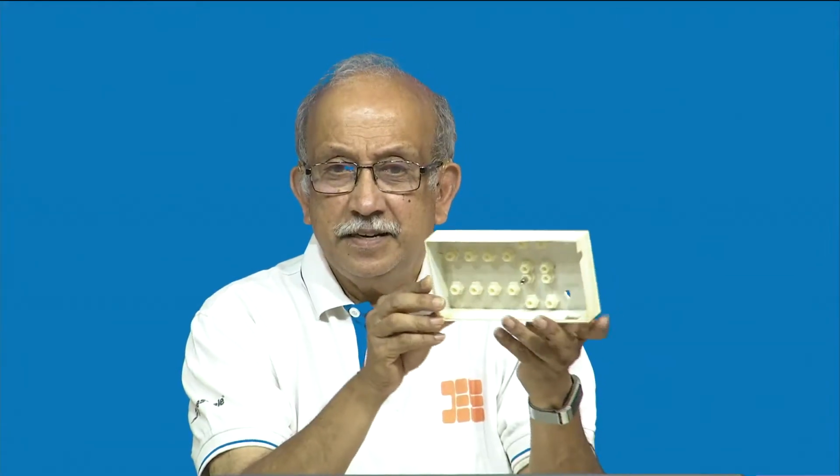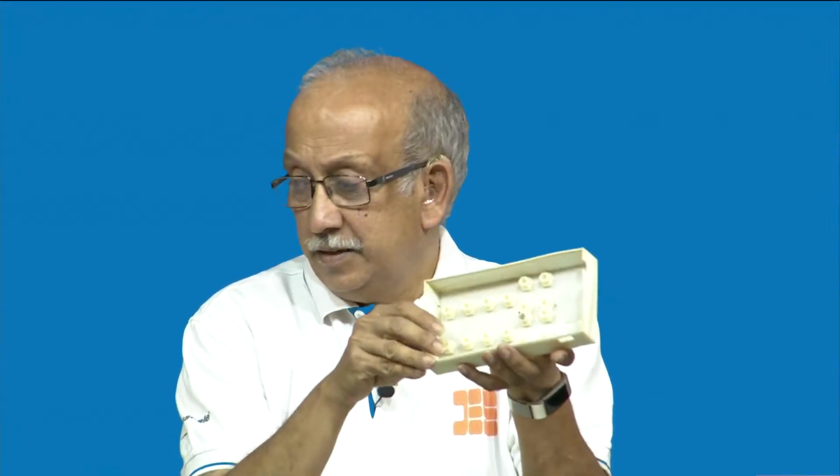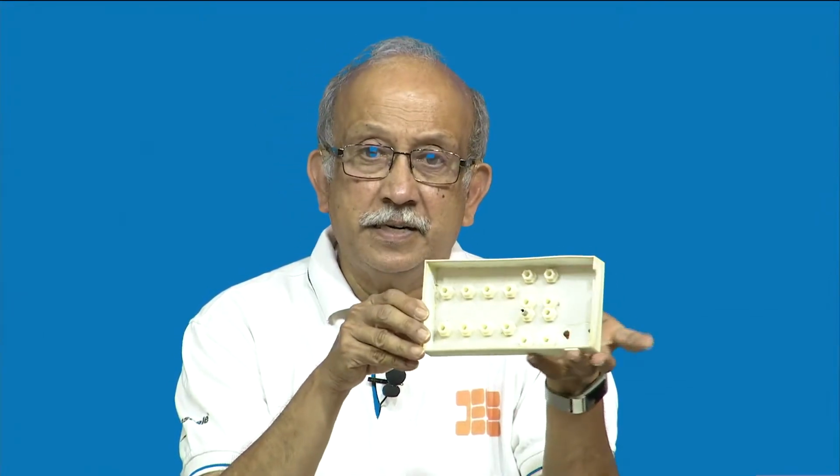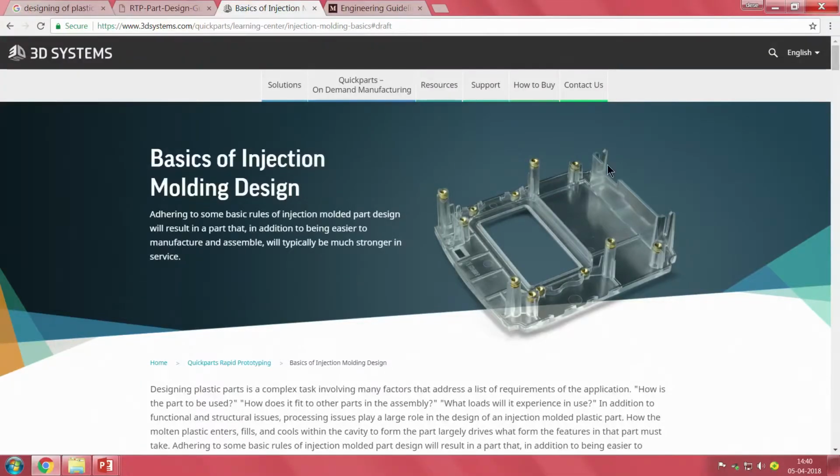This one is a 3D printed part, except the difference being, just like we have the issue in using these plastic parts, the detailing is very critical here. One of them is in case you want to have a metallic insert. You see here a lot of trouble has been taken, bosses have been made and the metallic insert has been inserted here. So, same thing if you see my picture here, see here this one looks a little like that.